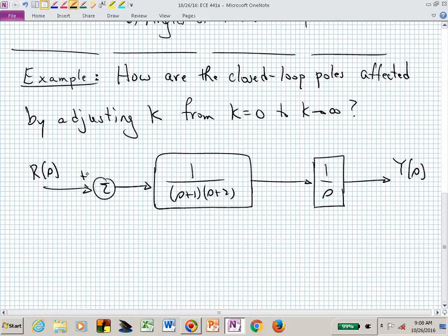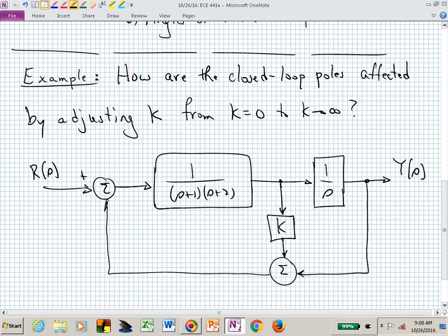On the far left is our reference input, but then we actually are going to measure that output y and compare it or add it in actually to the unintegrated signal coming out of that first block, and then feed that combination back to produce this difference of our reference input and this linear combination of signals coming in from the right. And so this is not the traditional block diagram, and we wouldn't expect to see this typical k in the denominator of 1 plus k g of s h of s that we might typically think is going to appear or be there.